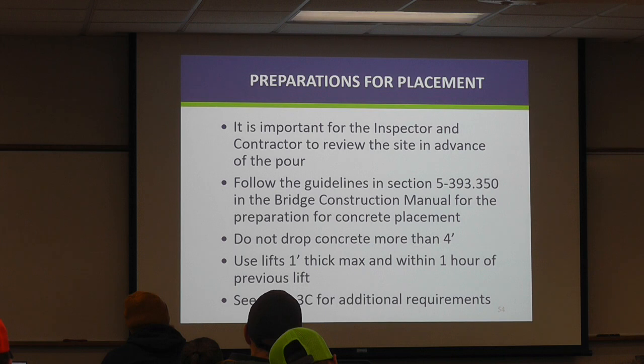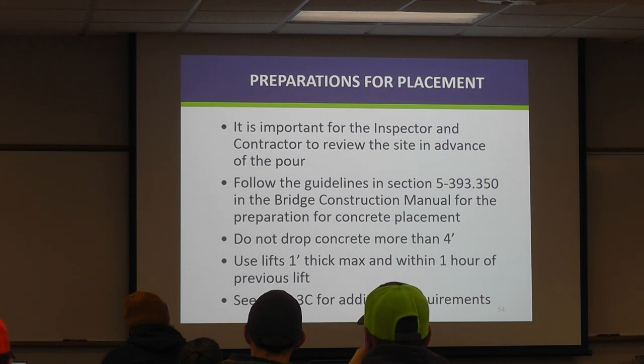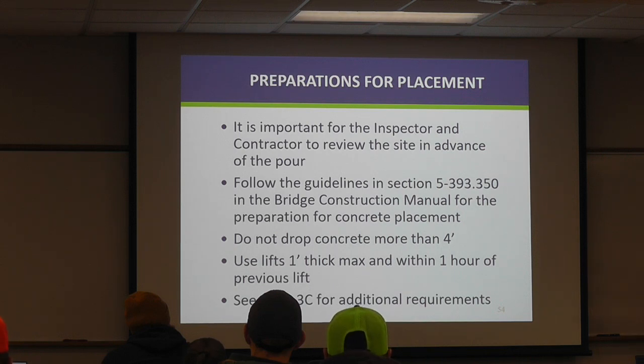Why? Anybody know? Anyone want to venture a guess? Segregation. So it's segregation that is the problem. We also want to use lifts 1 foot thick max. There's actually things in the spec that say you can increase that if needed in some situations.